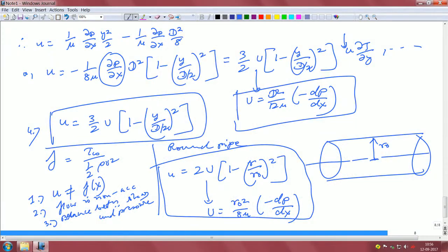Okay. And so, therefore, there you have to solve the whole momentum equation, which is what we did in our integral approach, right. Okay. So, you can see over here that once the flow becomes hydrodynamically fully developed, it has got an exact solution. That means in the energy equation, where you have basically u dT by dy and terms like that, it can be easily applied.